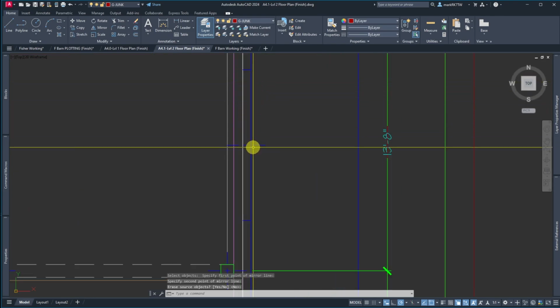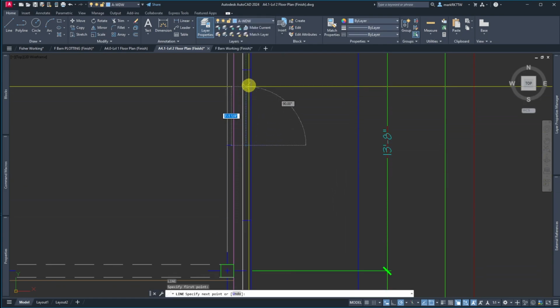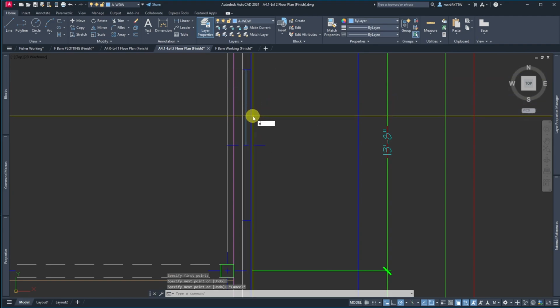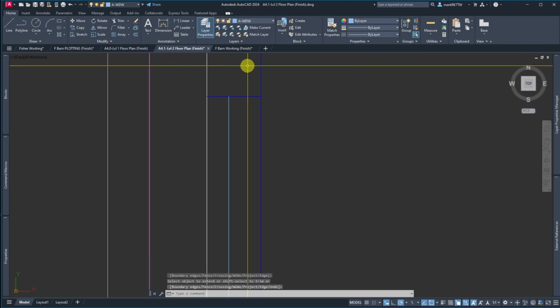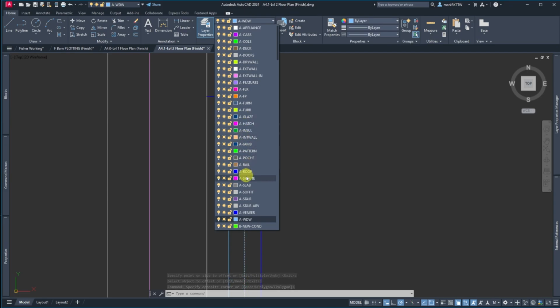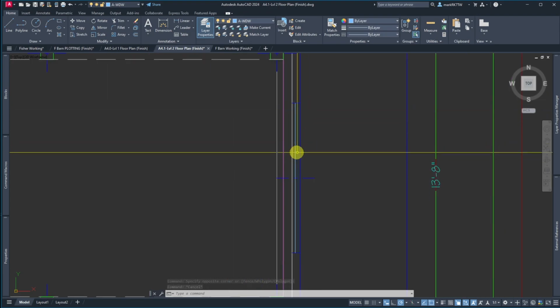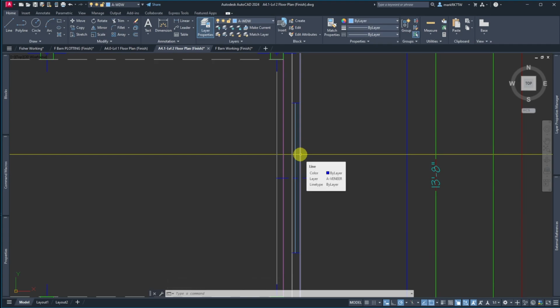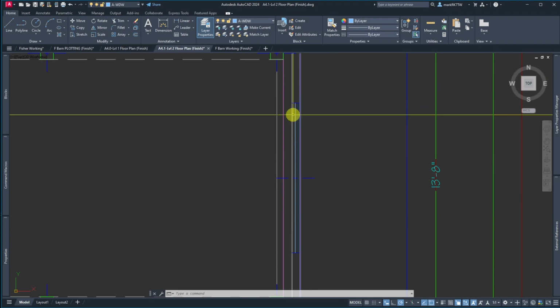And then I want to draw a window line. So if I want, I can go straight to a window and then draw a line from the midpoint of that until I hit there, and then extend it out to here, and then offset 1.5. Offset 1.5. And move that out. And then this goes onto what's called the A glaze layer. The reason there's 2 different layers is because we turn off the A glaze layer to put in headers and use this to drop headers to make it real quick and easy to lay out the framing. So it's starting to look pretty good. Indoors I would trim out that siding, but in windows I won't.